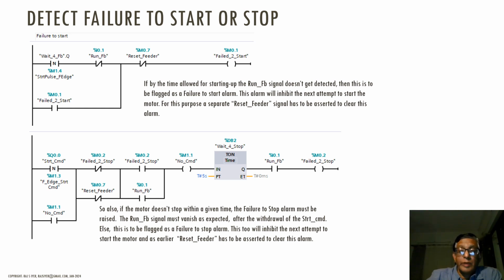But sometimes if the brake shoes or something gets worn out or due to other inertial factors or due to load, it is possible that the de-energized motor may start running by itself. And we are detecting motion, mind you. It's not merely the contactor going off. We are arranging the run feedback in a manner to detect movement of machinery or the flow of water in a pipe and things like that.